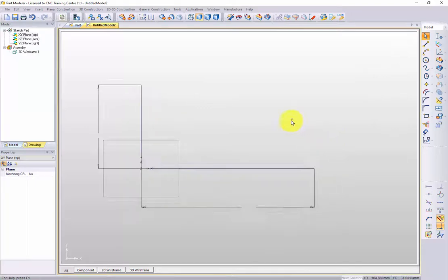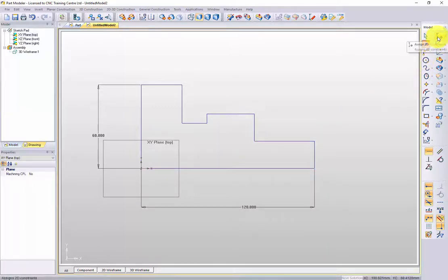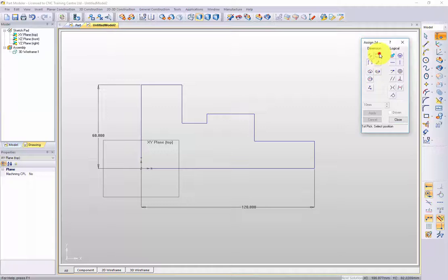So I've got these two lines which represent the outside of my shape, and then I'm just going to do a continuous line, this continuous sketch it's called, and produce the rest of the shape. So I'm doing that, coming down, producing my groove, producing this next diameter down to this final diameter. Should be able to just latch onto there and down there, and then effectively I'm going to add the constraints to that. So I'm going to do some vertical ones first.